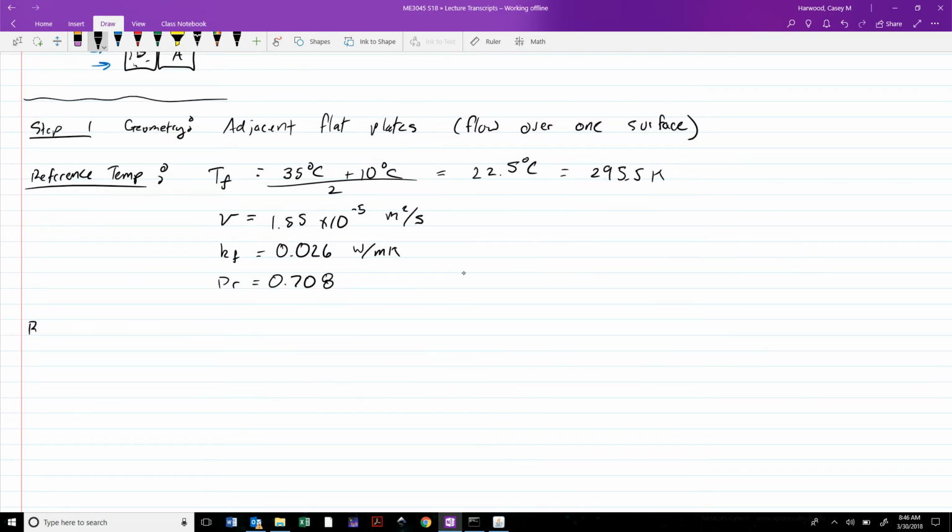So, it's your guys' turn. Who can tell me at what value of x the Reynolds number is going to hit that transitional magic 5 times 10 to the 5th value? This is going to determine how we take the following steps. This is for case 1, where we've got plates A and B. Does the Reynolds number reach 5 times 10 to the 5th while it's still on this plate, or once it's crossed over into the second plate B?